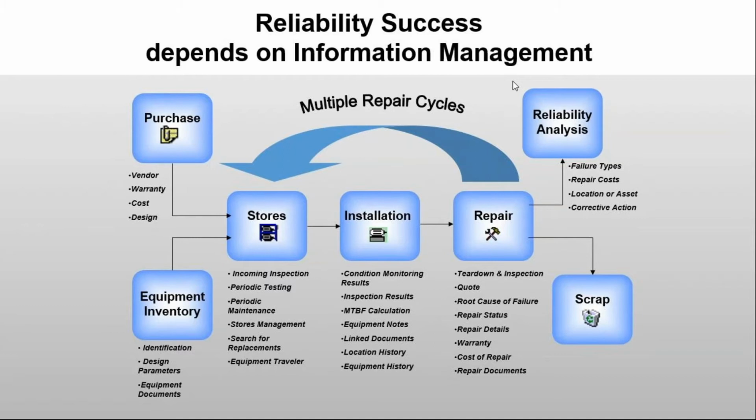At that point, pieces of equipment go to installation, and this is where we're going to spend most of our time today when we're talking about best practice number 3. There's a variety of things, vibration analysis, infrared thermography, oil analysis that are part of the condition monitoring suite of technologies that you might be implementing, whether it's through direct employees or service contractors. There may be equipment notes being taken during walk-around inspections, and out of that, you're developing histories of both locations and pieces of equipment. And that's what we're going to focus on in our talk today.